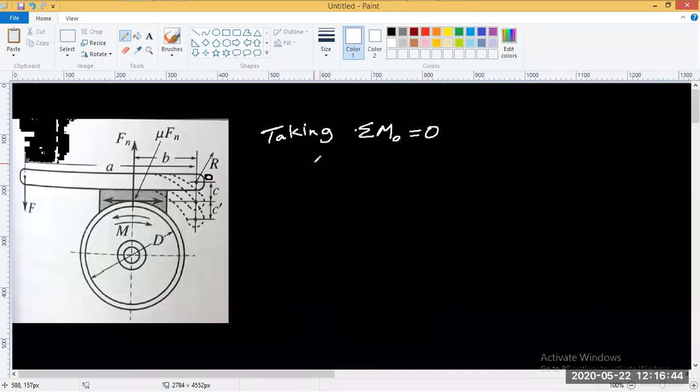Looking at the diagram, this is force times distance, sorry, this distance here. From this point, the force is applied along this distance, so this is inducing an anti-clockwise motion. Let's take anti-clockwise as positive. So F into k, and next force. The next force is Fn here. The Fn acting on this lever is inducing a clockwise movement at a distance of b, right? So clockwise, Fn times b.